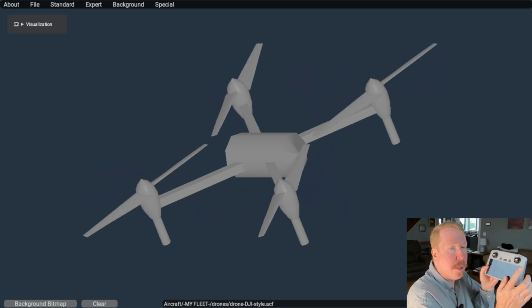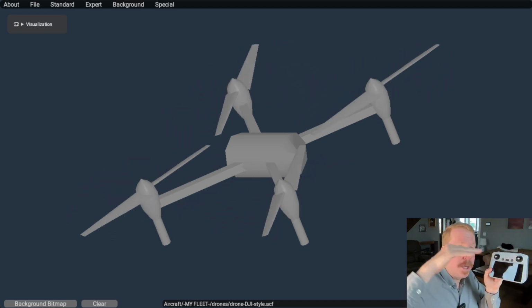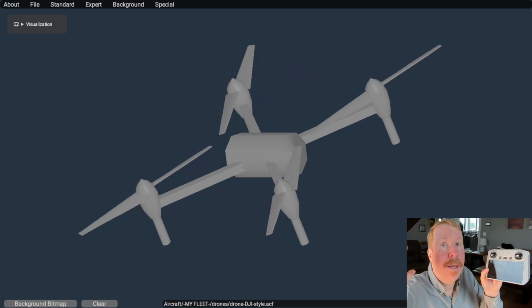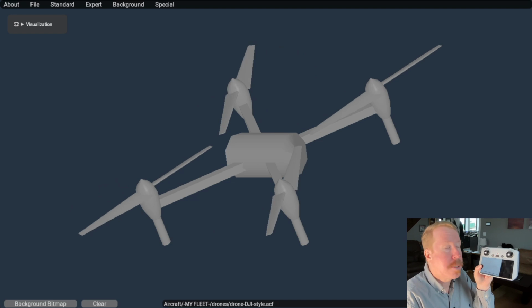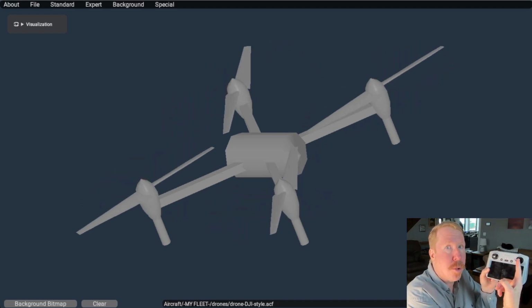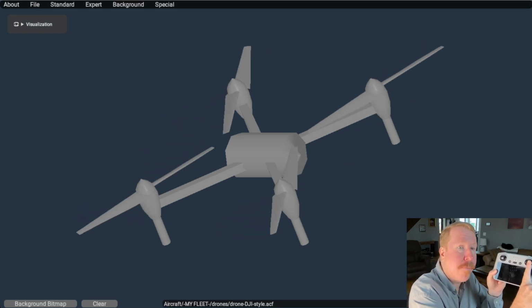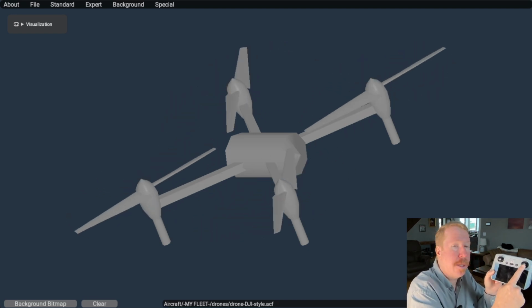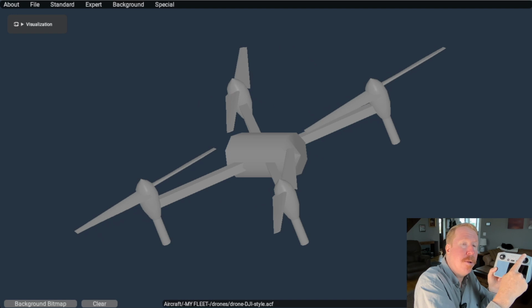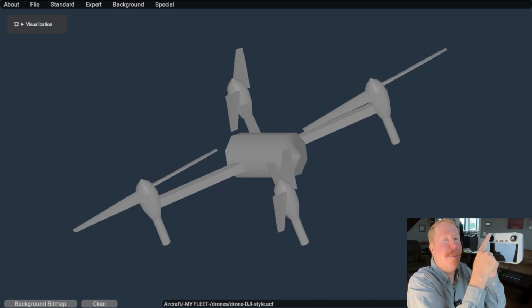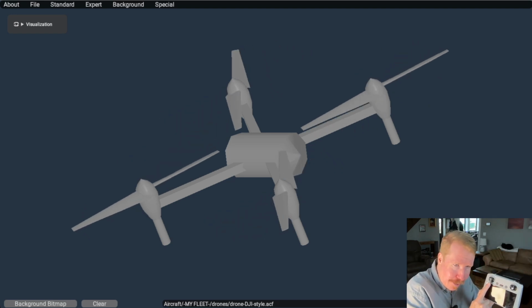How does it work? If all the sticks are untouched, the drone should hold its position in space, no questions asked. Just remain rock solid, still. This should control how fast the thing goes to the left in meters per second. This should control how fast the thing translates to the right in meters per second. This is translation forward in meters per second. This is translation aft in meters per second. This is translation up in meters per second. And this is translation down in meters per second.